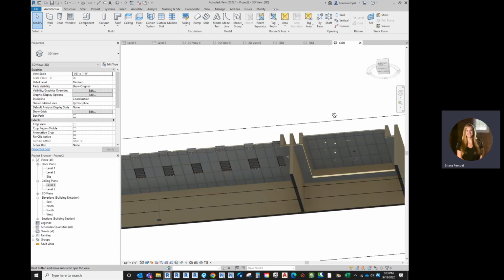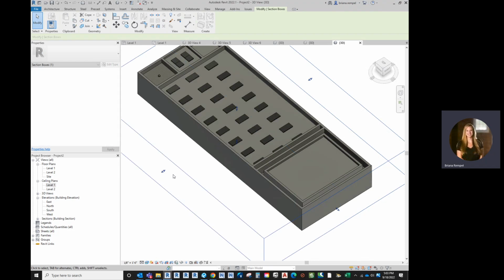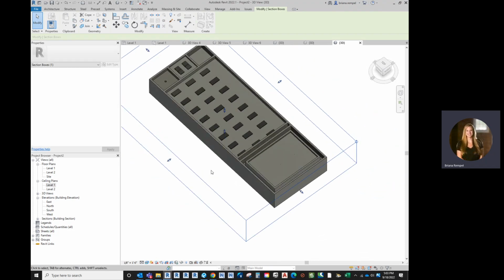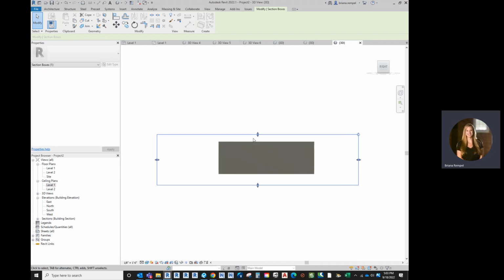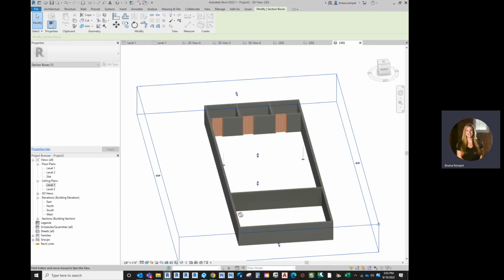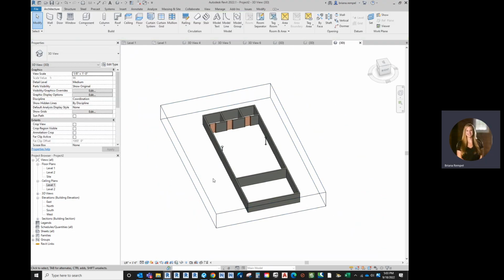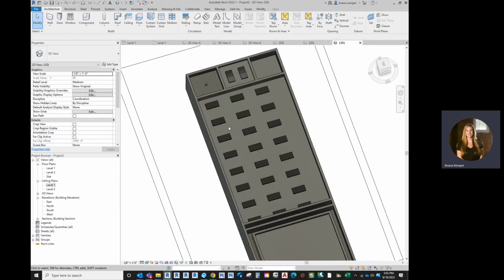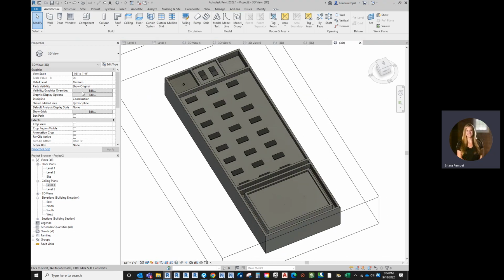You'll also notice with your 3D view that until we had ceilings, we were used to just going to the 3D view and being able to see all the way down. So two ways to get that visibility back. First way is to turn on the section box and adjust it, kind of square that view up, and you could adjust it below your lowest ceiling. But like this, you might be cutting off some other model elements you wanted to see. So another option, I just hit Control Z to undo that, is to go into your visibility graphics.